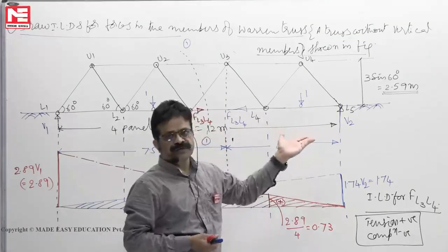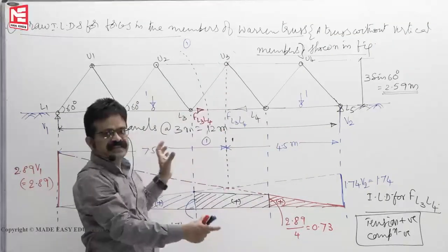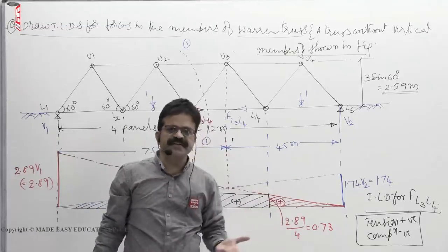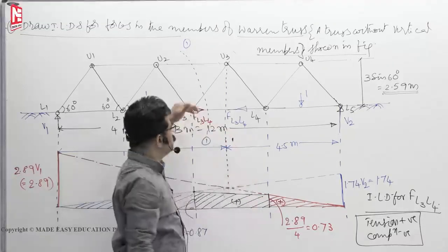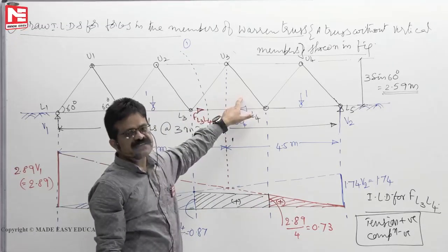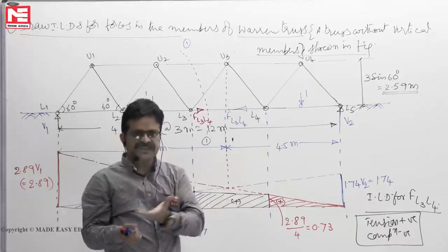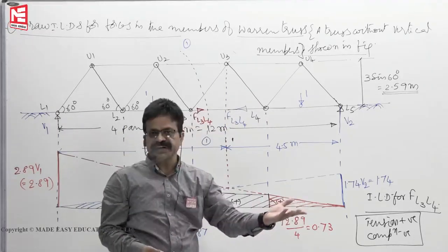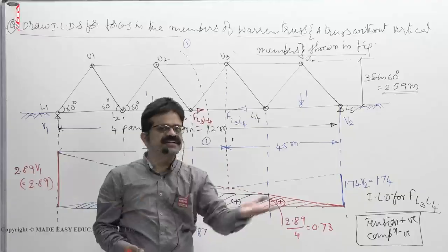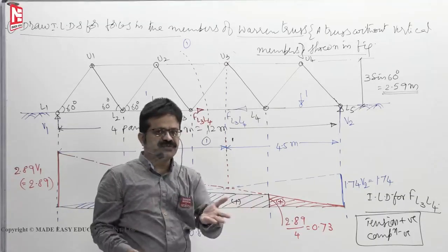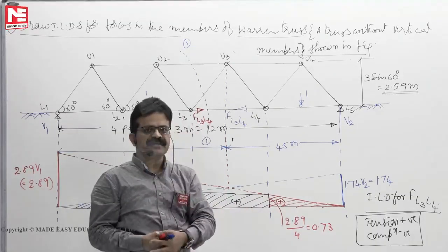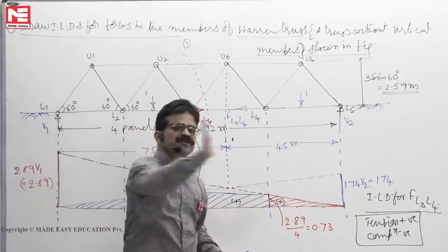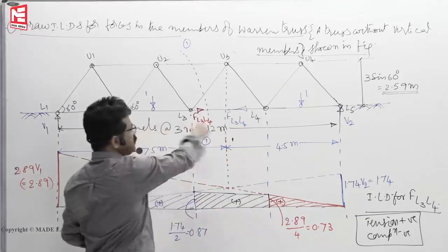Or earthquake load: suppose two columns are there here, and base isolators are there, then the compressive force transferred here is very less. If they are not there, the earthquake shakes the footing, let us say, then horizontally it pushes, and that force will be transferred to the column. The column will in turn transfer the load to the bottom members.